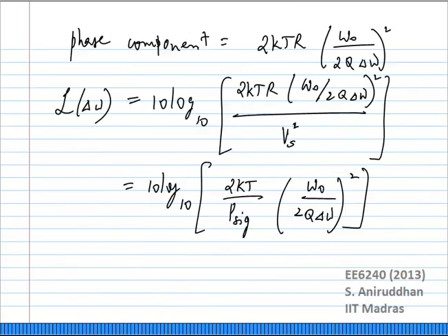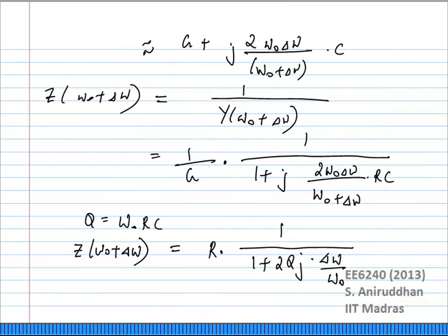So we have used G here. When we go down here, we have used G and R here. The really big point where it will actually impact you is in the expression of the Q. What you have assumed is that this Q is the unrestored, unloaded Q of the tank. In reality, the Q you have to use is the Q of the tank in addition with the energy restorer. And that Q will be a function of this delta F.